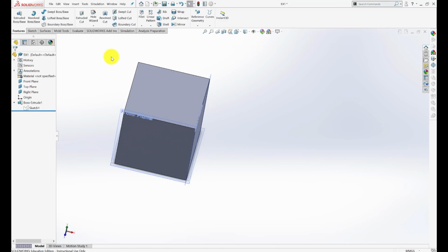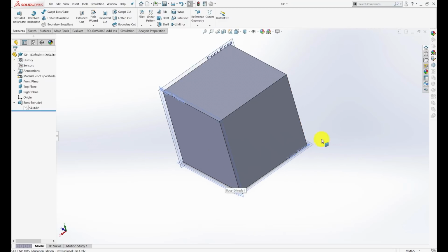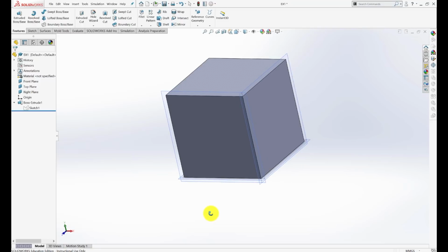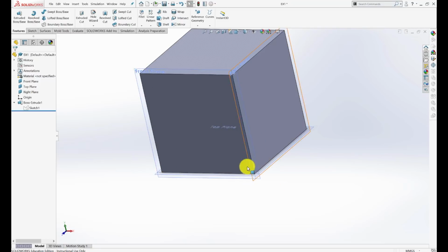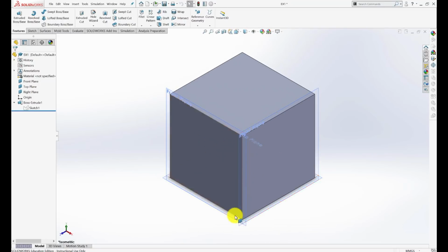Okay, so now just to hit this home just a little bit more, if I wanted to put a cut, a hole, right down the middle of this, I would do that by subtracting material. Now I like to be aware of where my origin is, and my origin is at the connection of these three planes. So I tend to like to look at things with my origin being this point right down here that's the closest to me. If I want to blast a hole in here all the way through, I've got a couple of options. I can do that from the top or I can do that from the bottom.